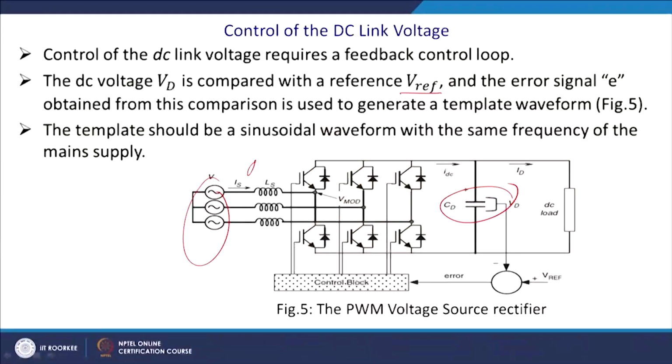Now, look, this is the voltage supply, thereafter is Is, and you have a source inductance. Generally you have to put extra source inductance; you generally require this value of Ls to be 0.05 per unit.